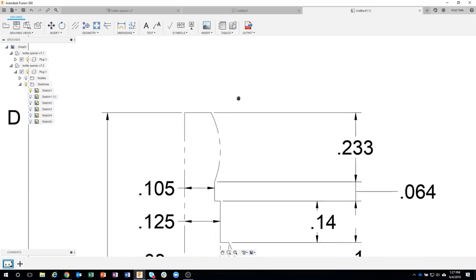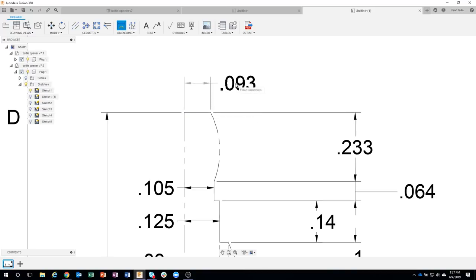Okay, so again, it's up to you. It's faster for me to click once and place the dimension than it is to come in and, oops, let me undo here real quick. To me, it's faster to click the edge than it is to go one point and then to the other point. But notice what I get here, okay? And this is kind of why I'm showing this, is I can choose which side I want the dimension on by the order that I pick the points.